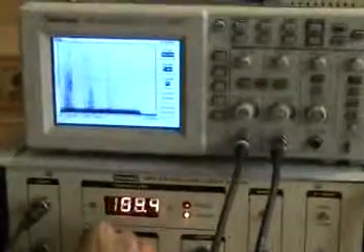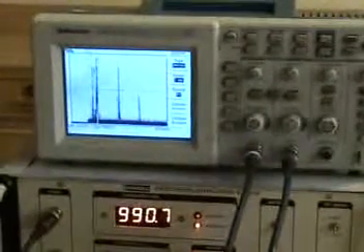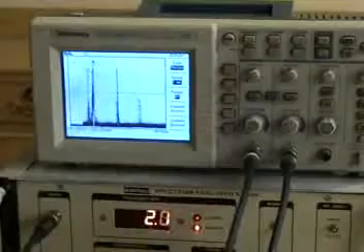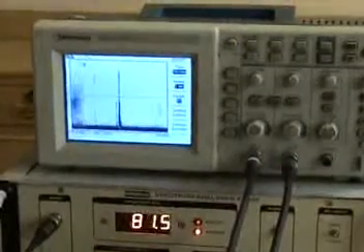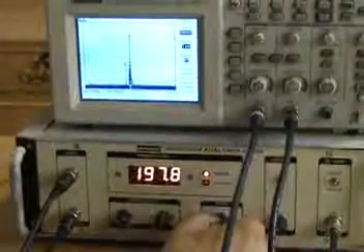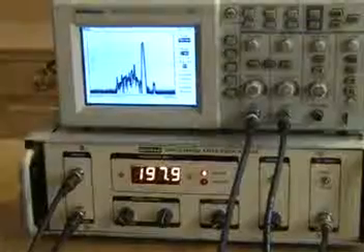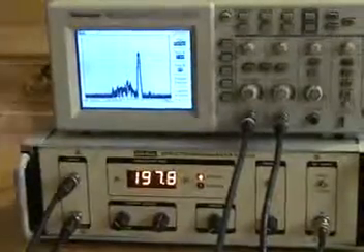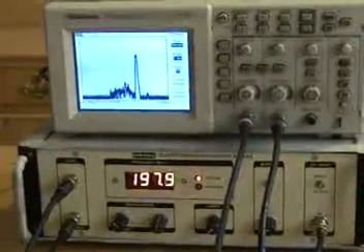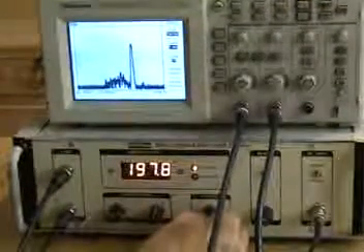So what we do is we'll bring the fundamental here, that is 200, and try to magnify it, and just switch it on first, and the signal is still higher. That is why you are seeing a lot of spurious. So we need to attenuate the signal so that it is not saturating the spectrum.